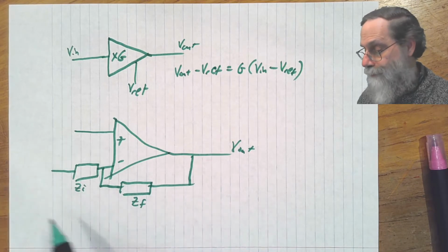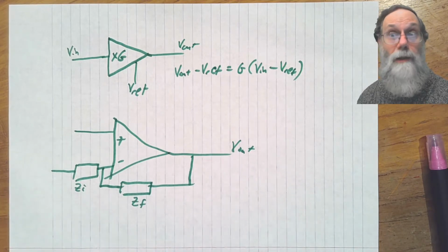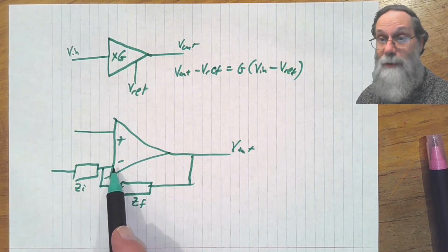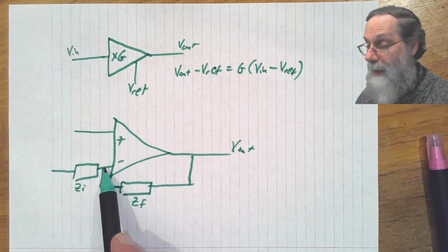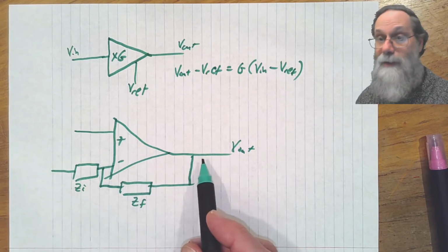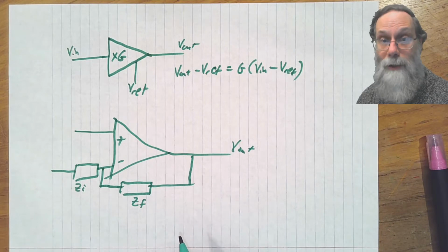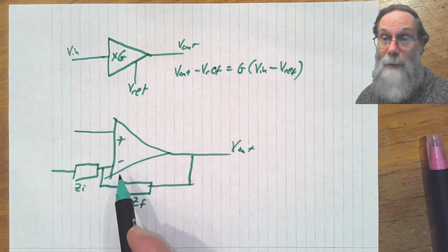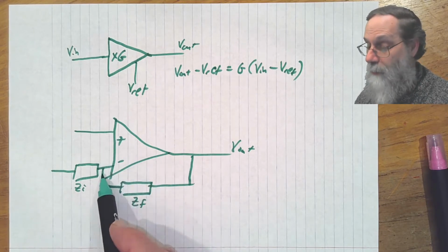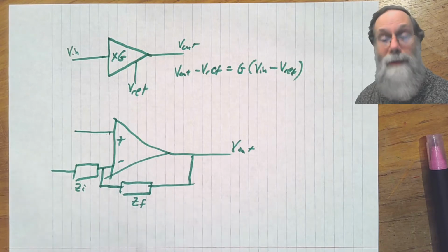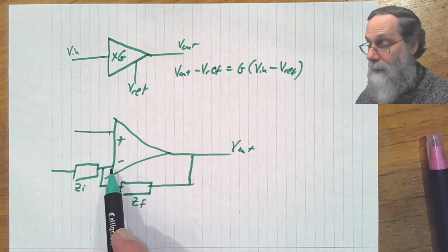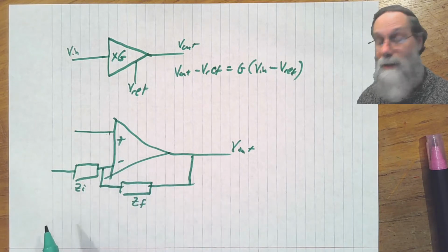So, and I just lied to you. This voltage doesn't actually drop. The input voltage here at the negative input of the amplifier, the negative feedback loop keeps that one clamped at the same voltage as on the positive input, because as long as V out is in the legal range, not hitting either of the two power rails, the huge gain of the op-amp means that the voltage difference between these two things must be tiny. So these two voltages are essentially always the same. That's an important trick for understanding op-amp circuits. Negative feedback holds the negative input to being essentially the same as the positive input.